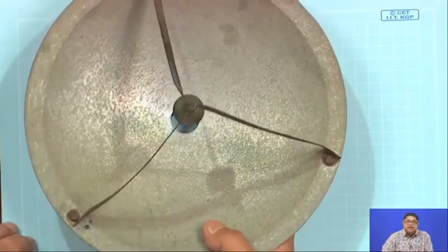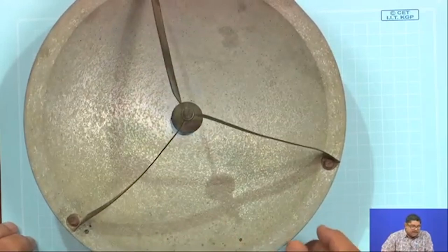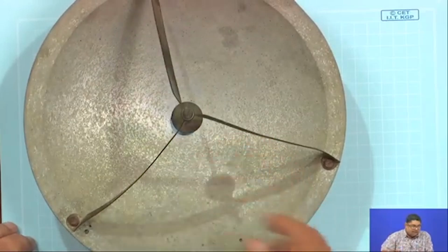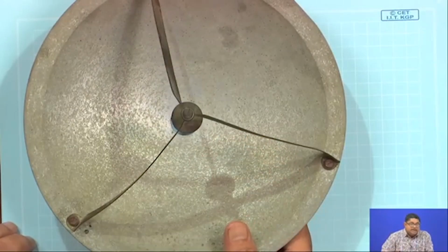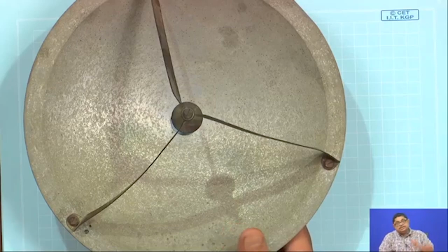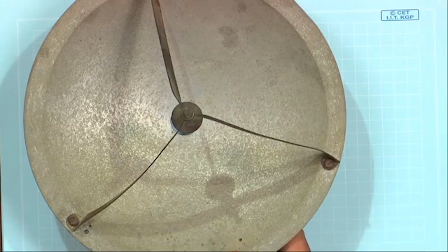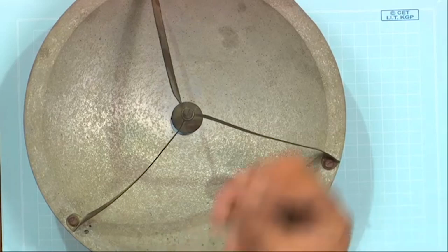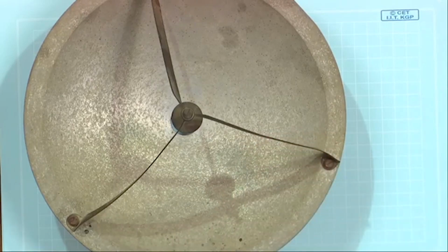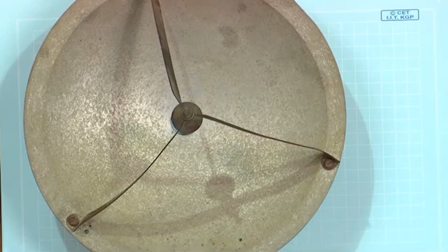With the reflector pointing towards the sky, the feed is pointing toward the ground. So, it will receive thermal noise from the ground, which reduces the sensitivity of the system, and that is crucial for radio astronomy people, because they do not want this thermal noise. Actually, their signal is so low that it is almost a noise. If this thermal noise comes, they will not be able to detect it.